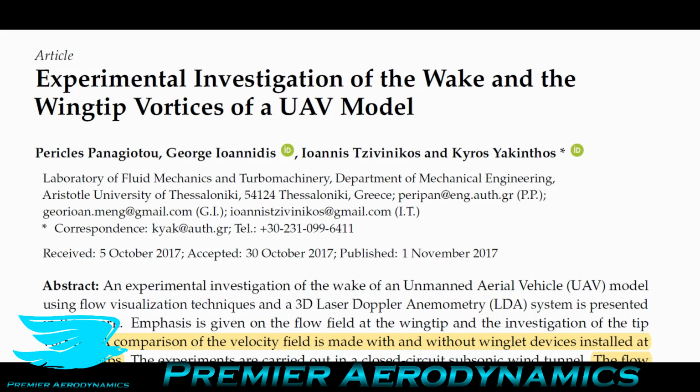And you can actually get a change in vortices. So if you have the bottom surface producing the lift, so the pressure side is now the top and the suction side is the bottom, you then get the reversal of that. So this vortex is really just a manifestation of a change in pressure between the two surfaces. It doesn't matter whether it's the top or bottom. And this is important because, as we'll cover, this is a main component of drag for an aircraft, particularly a fixed wing aircraft. It's called induced drag, and we'll cover what that is briefly down below.